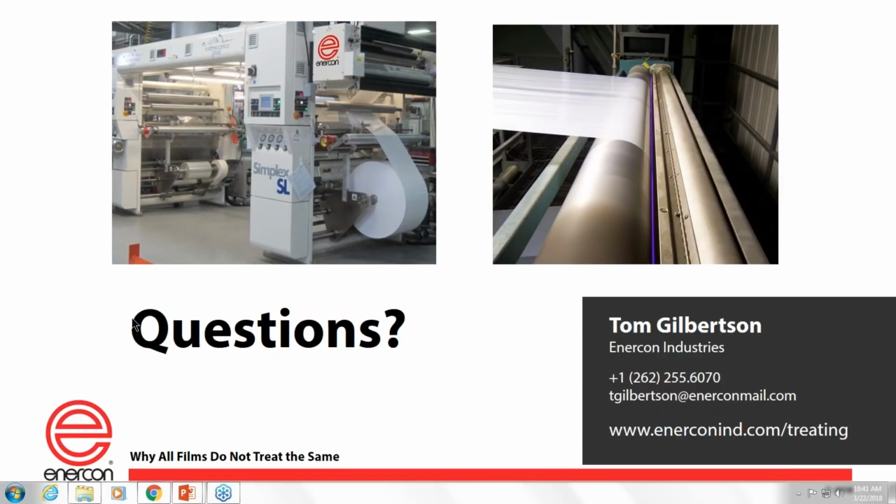And in that example, you might find air building up behind the web, getting some backside treatment, so the treatment on the top side, the side you want to convert, is not as good, and therefore your end result isn't as good. On the opposite end, where you can apply a little more web tension, maybe the result is better because you're not getting any backside treatment, and so your results are more to your expectation.